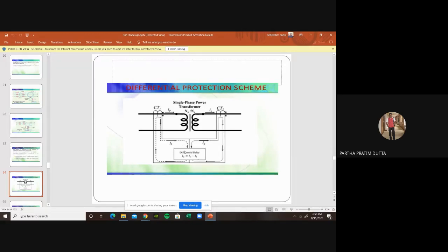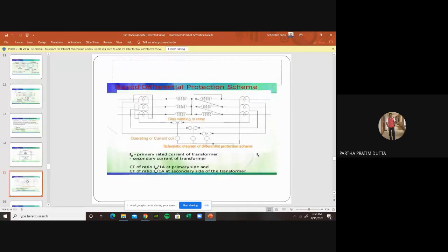So the differential relay is set in such a way that only when a fault occurs will the difference activate the differential relay, otherwise it will not. So when everything is normal, a little bit of difference of current is there due to the ratio, but that does not actuate the differential relay. But if any fault happens in between the transformers, the differential relay actuates. Not only the transformer, the differential protection zone is from 33 kV CT to 11 kV switchgear. So a huge zone is covered. In that case, a difference between the two currents happens, and the differential relay actuates, and the circuit goes off.